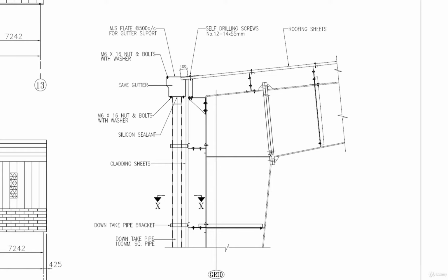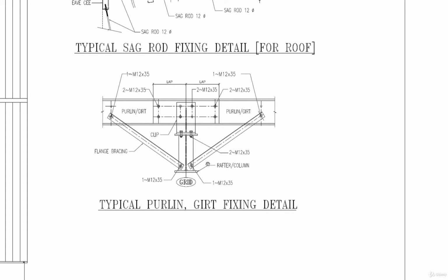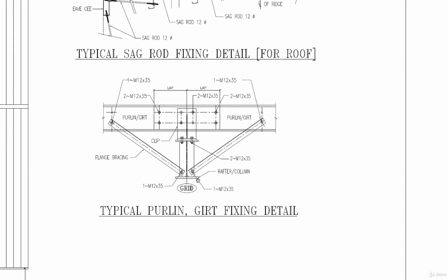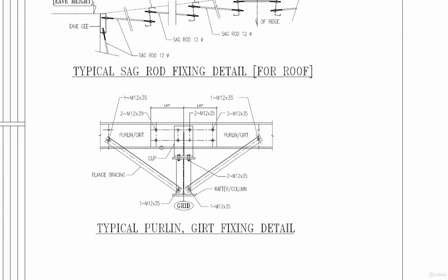We provide a plate here, we provide some stiffeners here, we provide some bolts here, so that 100% moment is transferred from the rafter to the column section. And this is a very important detailing that we do in the PB sections. What we are basically achieving here is tying the top as well as bottom flange of the section to the purlins. So here we have two advantages. Number one, the effective length of the purlin reduces, thus decreasing the size requirement of the purlin.